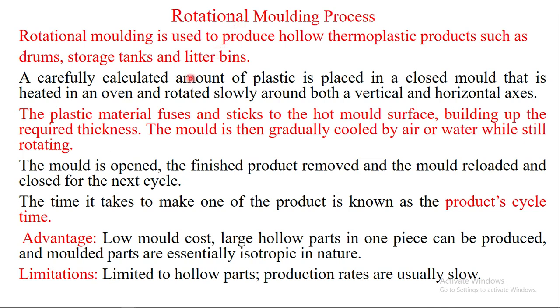Carefully calculated amounts of plastic are placed in a closed mold that is heated in an oven and rotated slowly. The rotation is around both vertical and horizontal axes. The plastic material fuses and sticks to the hot mold surface, building up the required thickness.